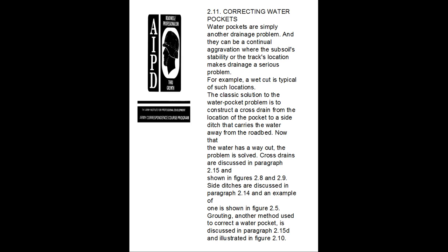The track can be leveled only by adding shims, bearing pieces of used rails, to the low spots. Since shims are placed either between a tie or a tie plate, or between the tie and the rail, draining the water pockets has to wait until the spring thaw. The amount of labor and material needed at this stage is much greater than that required earlier to eliminate water pockets. 211. Correction of water pockets.